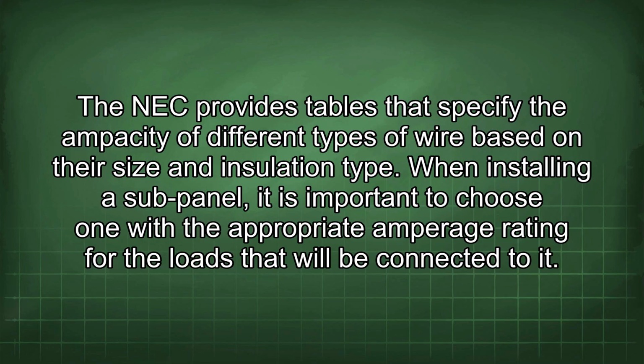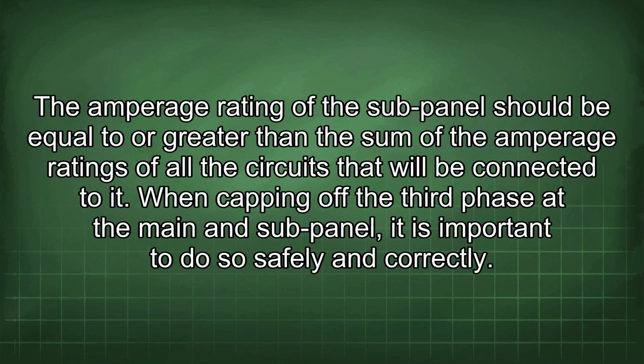When installing a subpanel, it is important to choose one with the appropriate amperage rating for the loads that will be connected to it. The amperage rating of the subpanel should be equal to or greater than the sum of the amperage ratings of all the circuits that will be connected to it.